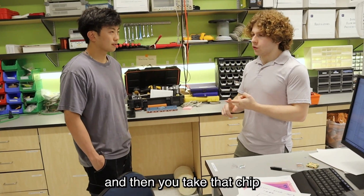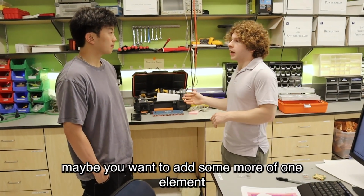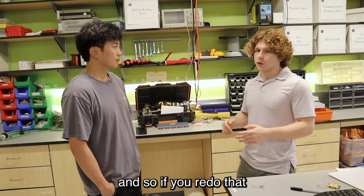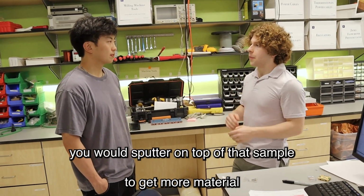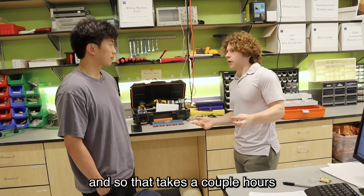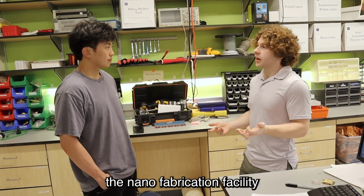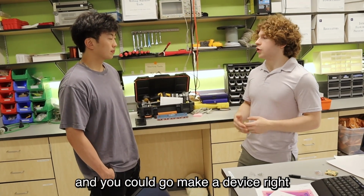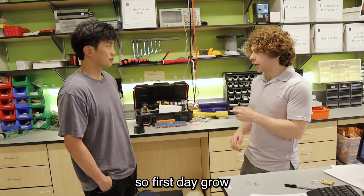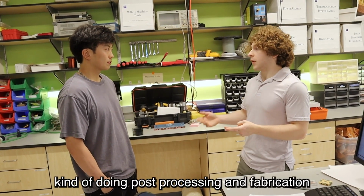And then you take that chip and you do some post-processing on it. Maybe you want to add some more of one element, like aluminum, or tantalum, or niobium. If you were to do that, you would sputter on top of that sample to get more of the material. That takes a couple hours. And then on that same day, you could go to the clean room, the nanofabrication facility, and make a device, right? And so that's another day. So first day growth, second day kind of doing post-processing and fabrication.